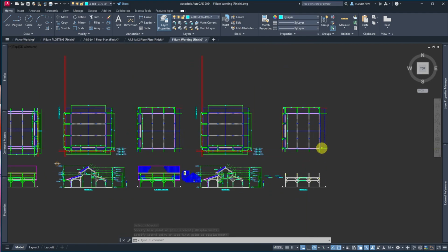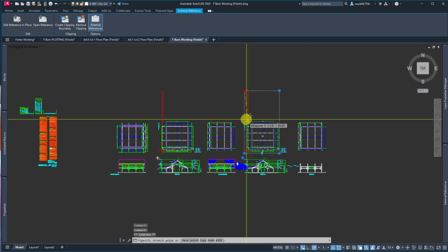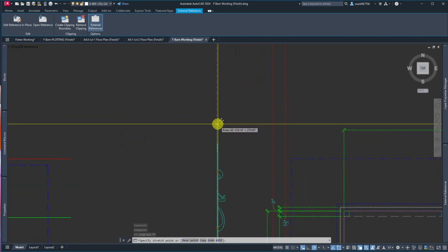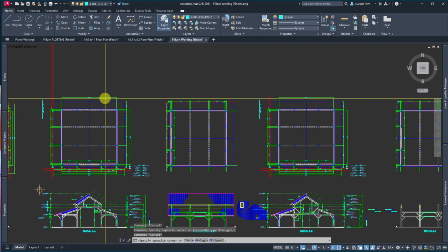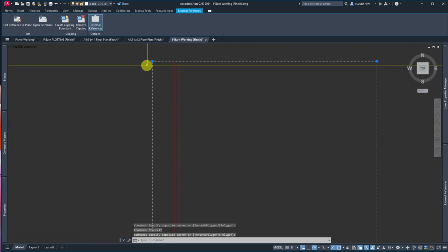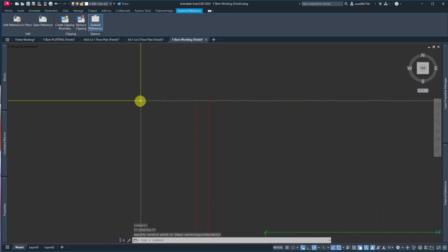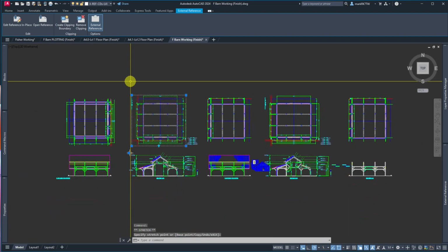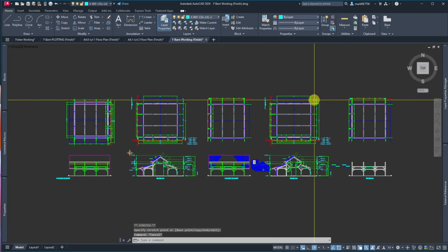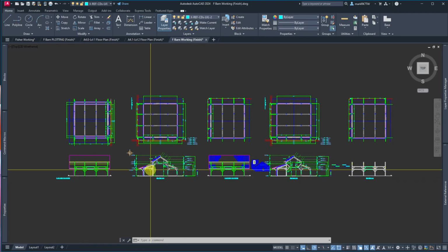I've got an extra artifact here anyway. Now let's move these down. Looks like I've got too long of a section still up here. Let's bring that down and get it in nice and tight. And let's see what our other ones look like. So that one's good. This one, we need to bring that down. Let's get in a little closer so we can see where we're at. Make sure we're not hitting our number to the far right over there. That's probably good enough. And then we're going to move all 5 of those, and we'll create our elevations. We'll do this as the front.